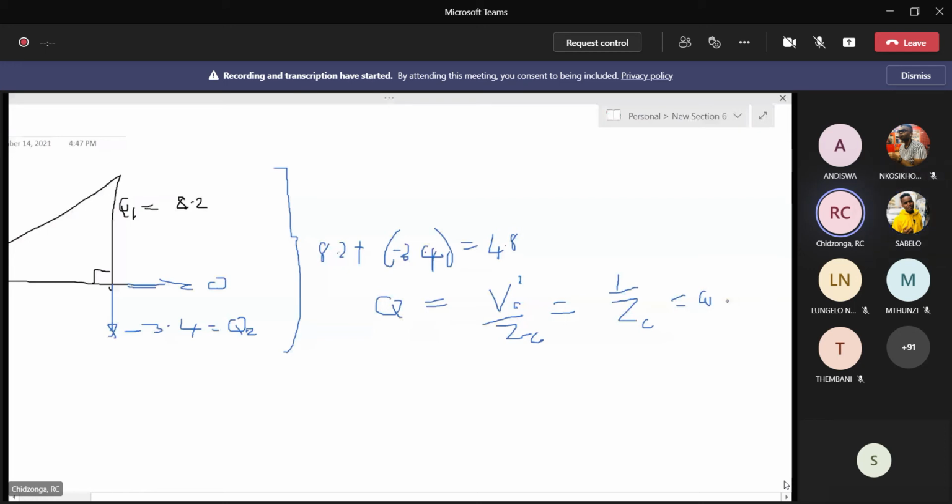Remember, the impedance of a capacitor is 1 over omega C, the magnitude. I'm talking about magnitude, right? Yes. So if you take the inverse of this, it just gives you that 1 over omega C. And therefore, we are saying that omega C V_C squared should equal 3.4 times 10 to the power 3. Remember, that is kilo. All right?